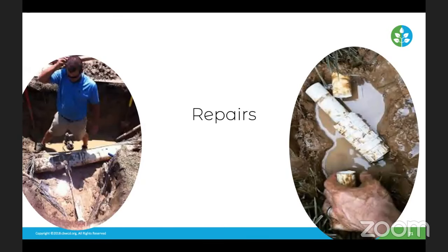Depending on the type of irrigation valve you have, typically they're plastic. So it's plastic on plastic. I always recommend to not use the external bleed screws that often for that reason, that they are plastic on plastic and they usually have an O-ring. And if you are constantly opening and closing them, they tend to leak over time.